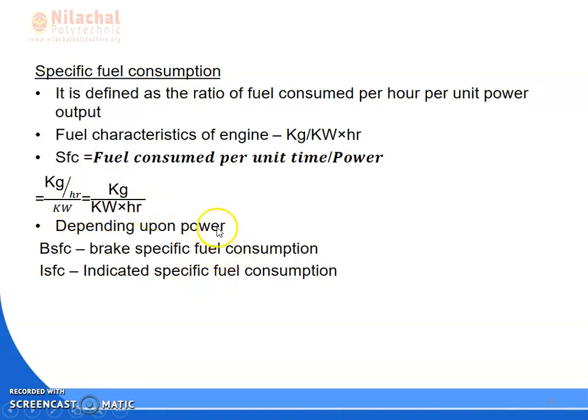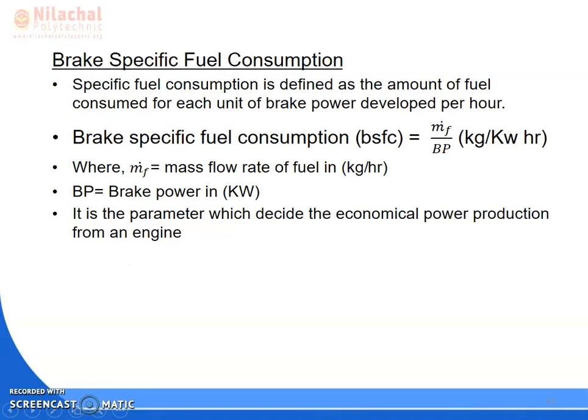Depending upon the power, the specific fuel consumption may be brake specific fuel consumption or indicated specific fuel consumption. Now we will discuss brake specific fuel consumption, that is BSFC. What is brake specific fuel consumption? It is the amount of fuel consumed to produce unit brake power per hour.